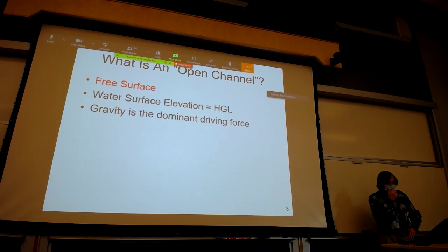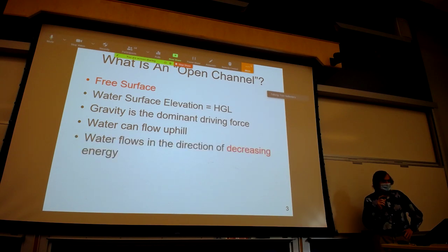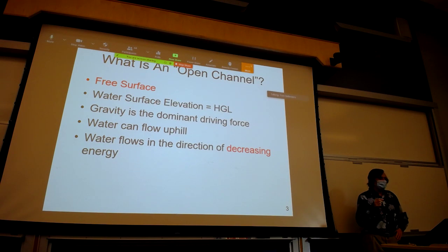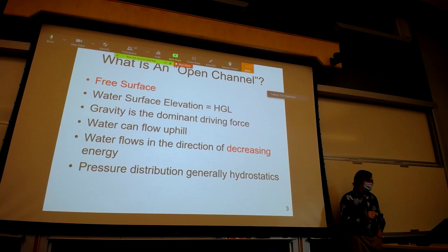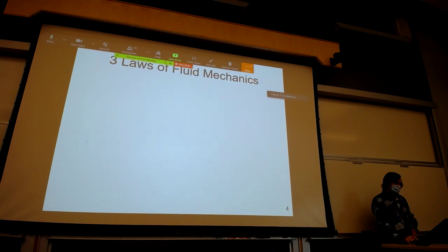For open channel flow, gravity is the dominant driving force. However, you should know that water can flow uphill, and you see this happen every day, you just don't think about it. Water, or in the general case, fluids, flow in the direction of decreasing energy. That's what's important. Somehow that very last bullet, fluids moving in the direction of decreasing energy, conventionally or colloquially transferred to water flows downhill. Water does flow uphill. And then generally in open channel flow, what we have is fluid statics occurring, and I'll describe that a little bit more in future slides.